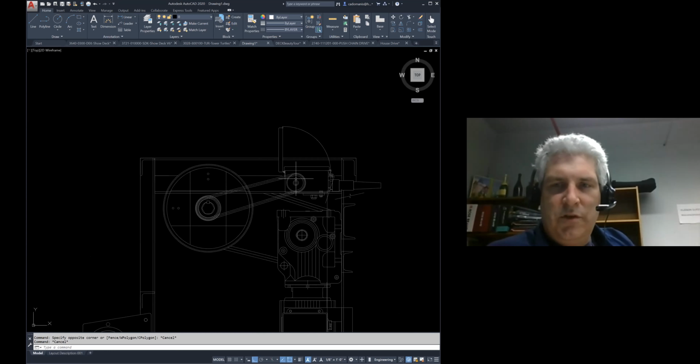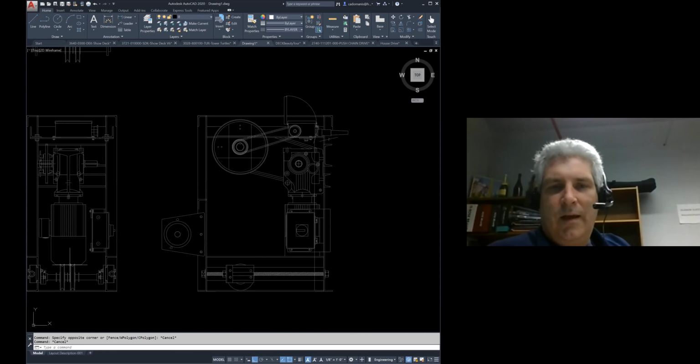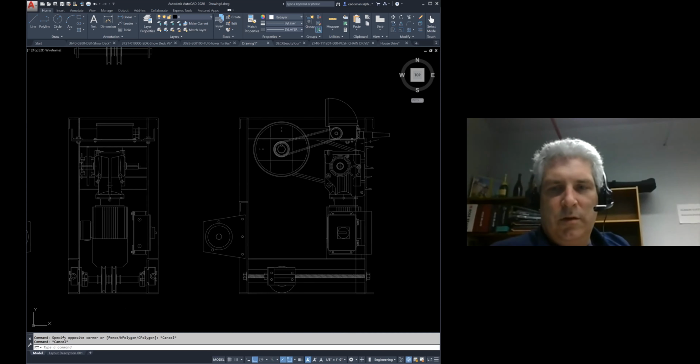Usually these days, machines involve some sort of feedback device, so that we can go back to our control systems. In the case of our Hudson winch, we have a little box here we call the limit box that has a rotary limit switch that we use for end of travel limits, and then an encoder inside that box that we use for positioning. And that, again, we have just a little roller chain stage that connects the rotating drum to that limit box to go through that travel. In many systems, you will also have either an encoder on the motor, either that encoder and not an encoder here, or a secondary encoder on the motor. Kind of depends a little bit more on the controls.